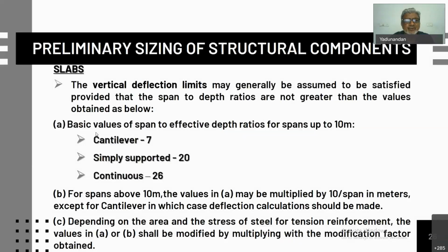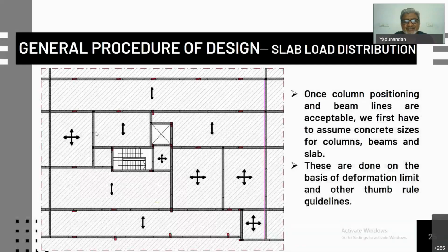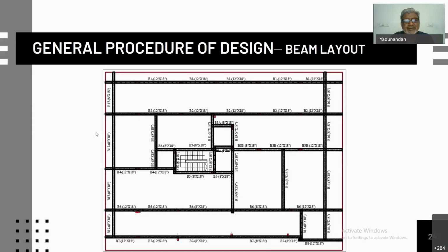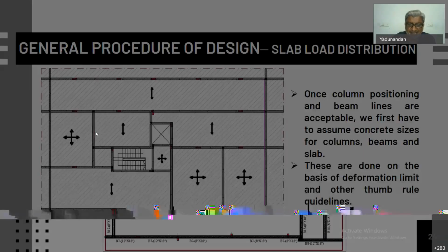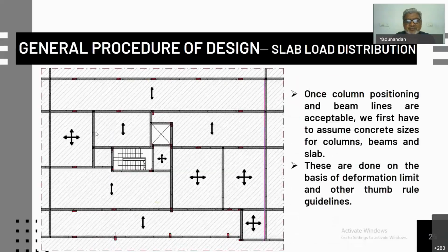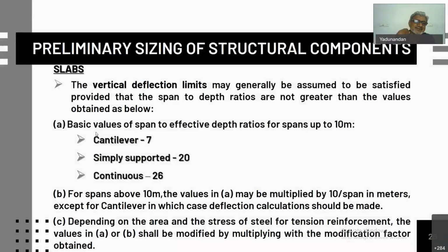We therefore consider the preliminary sizing of the structural components. Mainly, in fixing up the sizes of the slabs and the beams, we use the serviceability considerations of deflection, which are more important to fix up and guarantee. Based on that, we see that depths are such that the deflection is not going to occur, and we make sure about that, and then provide those basic sizes and go ahead with the analysis. In selection of these sizes, how do you do that for slabs, beams, and columns?